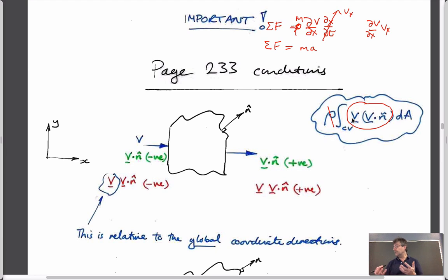The reason is the same as in Bernoulli, where we have v squared over 2g. That comes from a rate of change of velocity with time, equated to Newton's second law. So this acceleration looks like these two components, a velocity times a velocity, and we can also write this as a half rate of change of velocity squared, if you recall. So it doesn't matter.